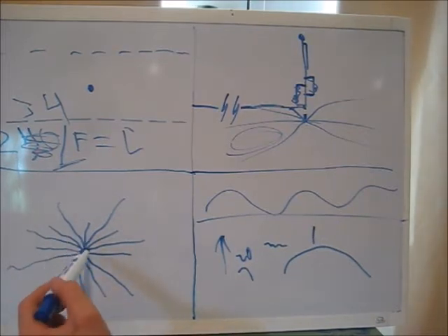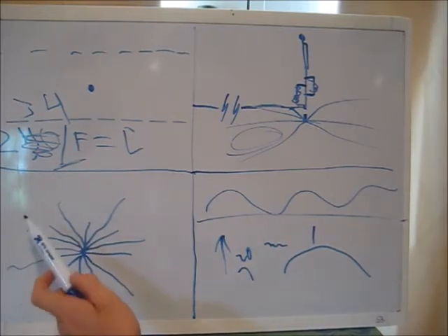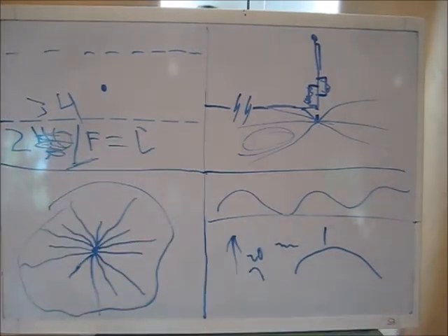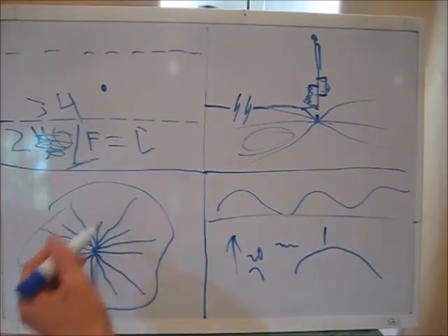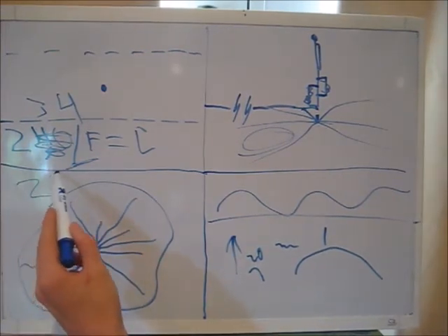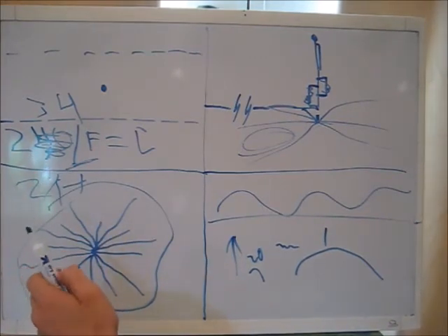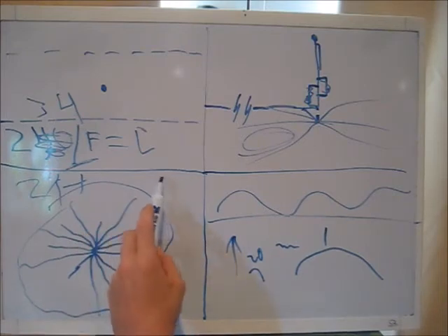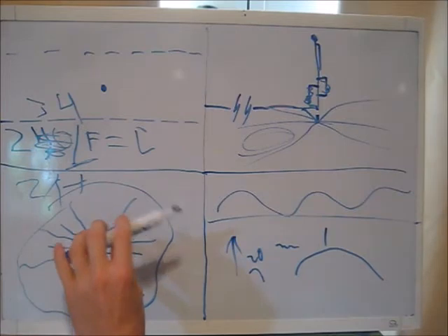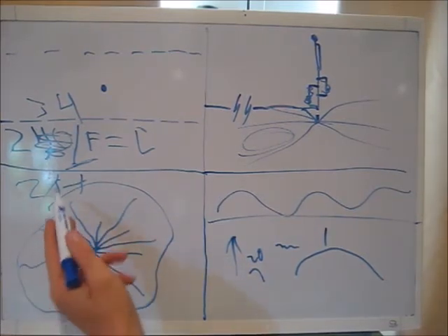The more radials, the less ground loss. And, big bonus, the more radials you put, typically the lower SWR you're going to have. I have found that doubling your radials from 2 radials on 40 meters to 4 radials on 40 meters drops my SWR by about 0.2. So it went from 1.4 to 1 to 1.2 to 1, which is a substantial change from almost unusable to perfectly usable. And that's just a little run through on verticals.